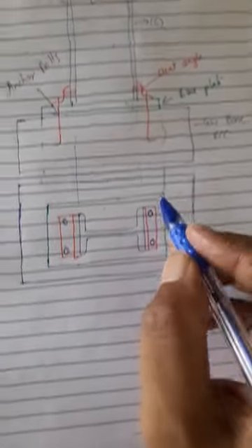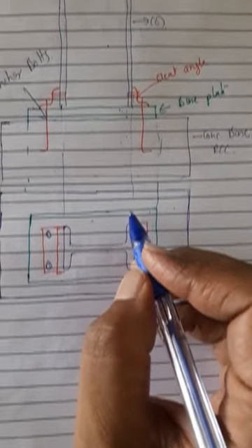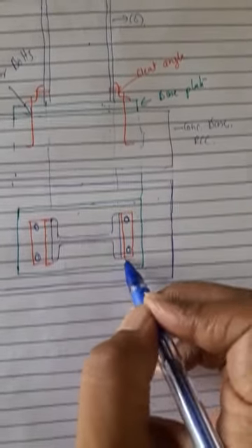If you look at this diagram, this base plate projects outside the I section. I am going to keep this projection and this projection the same for economy and ease of construction.